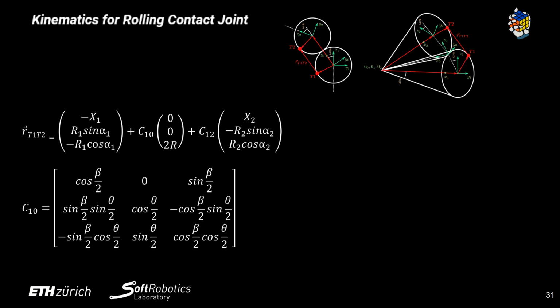To get the motor displacement for a specific joint, the angle combinations are important. We just need also to subtract the exposed tendon length with all joint angles equal to 0. This value could further be used in control algorithms of the 5-hand.